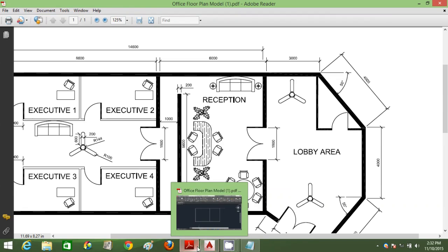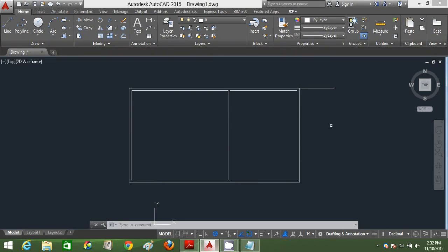Using polar relative coordinates, right? The angle that you enter in AutoCAD must start from the 0 degree axis. So you just type 4000, and the angle is actually 360 minus 50, getting the corresponding angle 310, right?